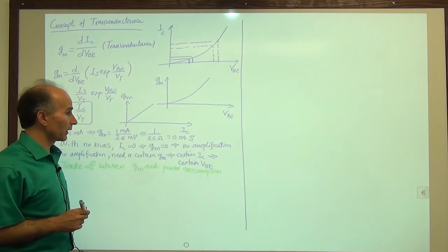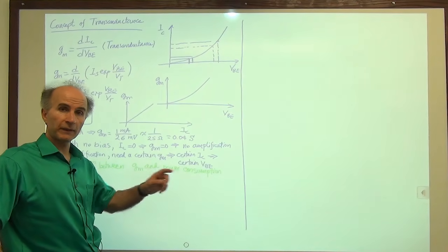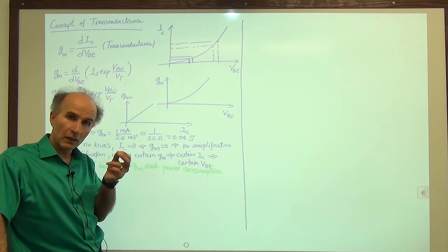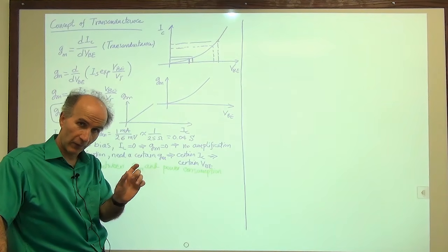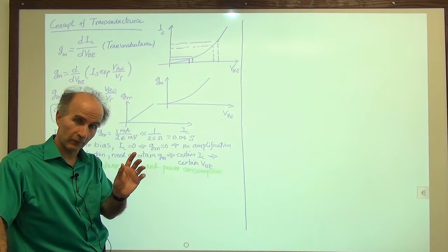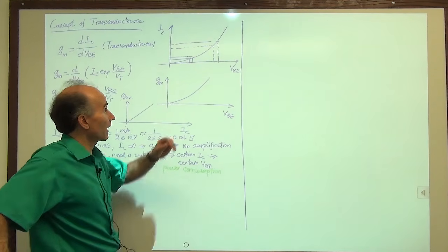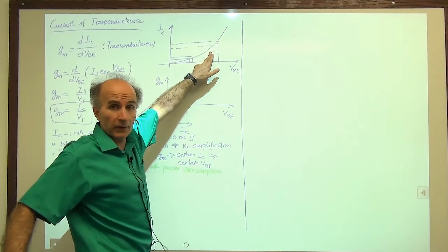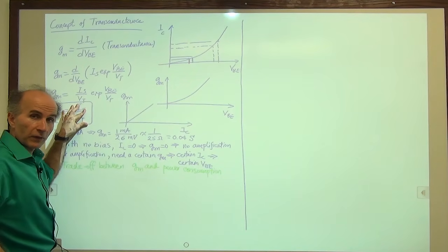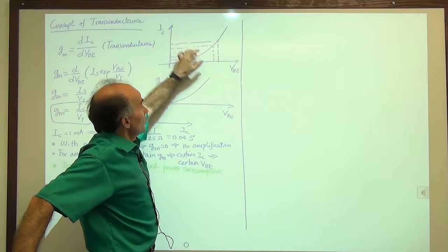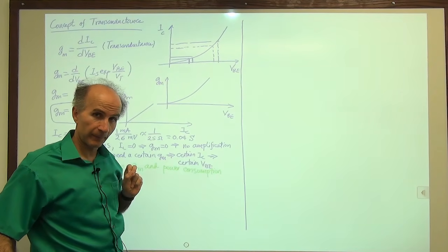Okay, so one other point is that from our calculations a moment ago, we realized that 10 millivolts, that 10 millivolt increment that came from the microphone and it was applied to the base emitter voltage was not considered a small value as far as calculating the slope is concerned. When we calculate the slope using this equation versus this change over 10 millivolts, we see that the values are a little different.